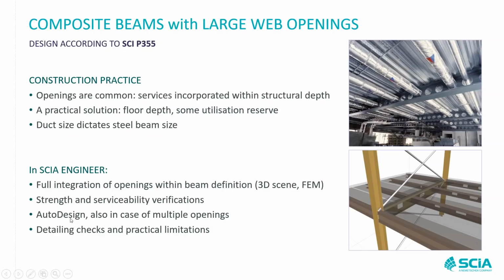Then the next thing we do is we have the strength and serviceability verification. So for strength, we go for publication SCI P355. And for serviceability, we take into account the additional flexibility based on the finite element results.